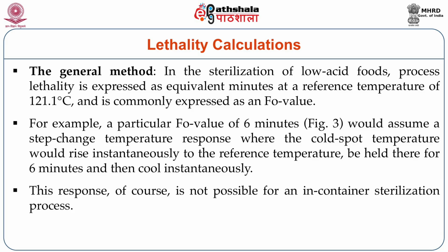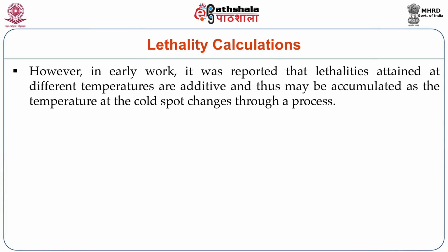As shown in the figure, it is not possible for an in-container sterilization process. However, in the early research work, it was reported that lethalities which are attained at different temperatures are additive and thus may be accumulated as the temperature at the cold spot changes through a process.